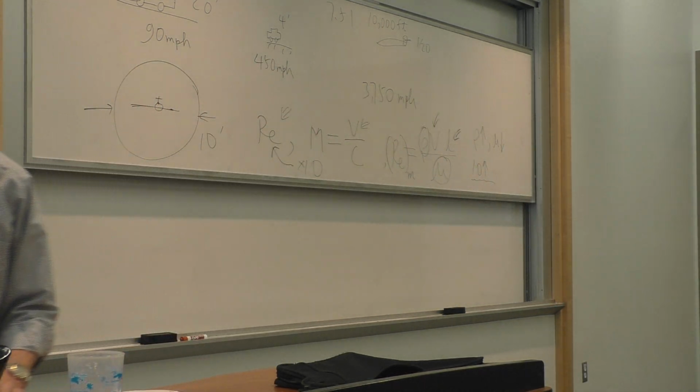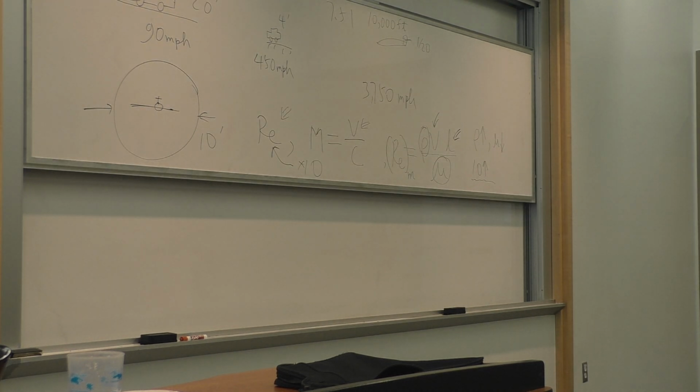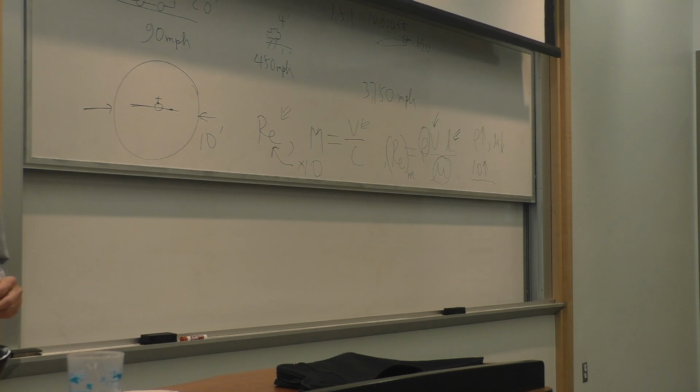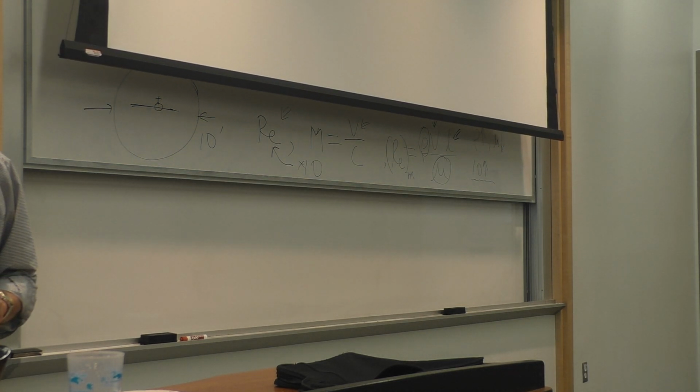Are you sure? Think about it and try it one more time. When you heat it, what happens to the density? It decreases. You want to go the opposite way, right? I just cover the screen. You want to what to the density? You want to increase it. How do you increase density? From ideal gas, how do you increase density? Ideal gas. Decrease temperature and increase pressure. You got it.